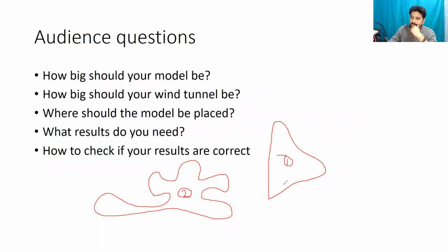Any guesses? If you are a chief aerodynamic engineer for a team, exactly, that minimal drag force. Aditya, why is that? Long straights, so low downforce. Well, low downforce is desired, right? You don't really care about downforce. And in this case, the only thing that you're looking for is lower drag. So that is what you need to optimize for, meaning every component in your car needs to be set up in such a way that you have low downforce.